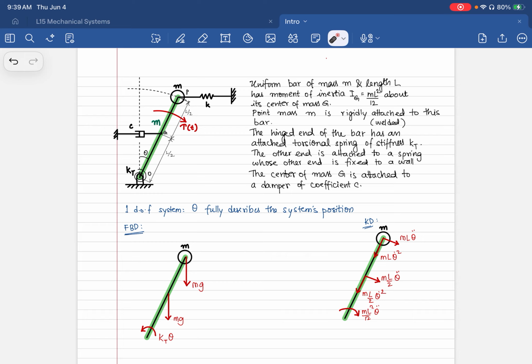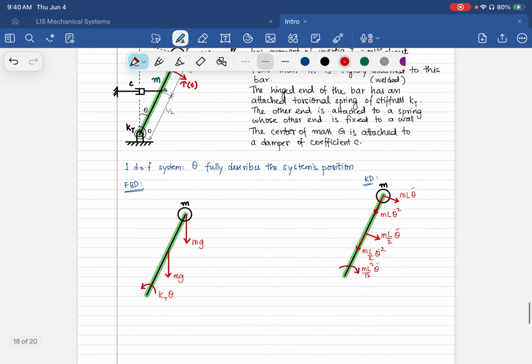So if you were to look at the rotation here, this is an arc that is set up wherein you have a radial length of L and the rotation is theta, which means that this arc length is L theta. So your spring from its natural position that is over here is being deflected by L theta, and you can see that it's going to be in compression.